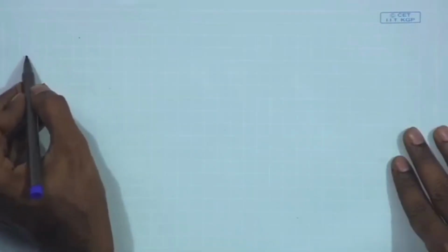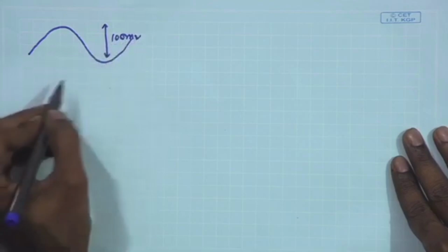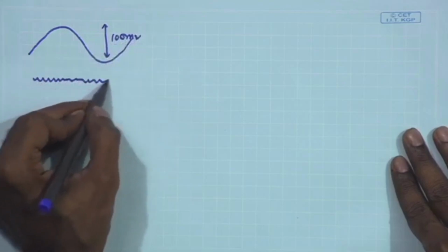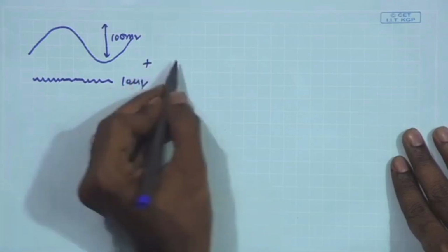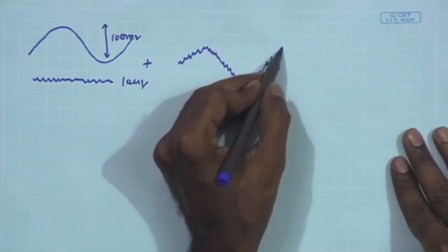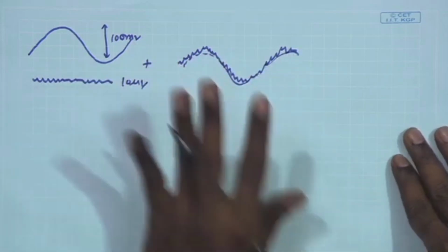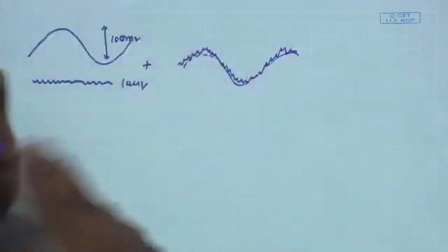Along with that, we have discussed in the beginning that the signal specification can have a very wide fluctuation in the baseline. If you remember the discussion in the beginning when we were trying to set the specification of the front end amplifier, we noticed that the baseline can have a huge swing, few hundreds of millivolts, and on top of that you have the tiny signal sitting, which is maybe 10 microvolt or 100 microvolt. So the actual signal that you are getting is the small peak to peak desired signal sitting on a highly undesired, large signal which needs to be rejected. So this is another non-ideality. This is coming from the signal part that also needs to be addressed.